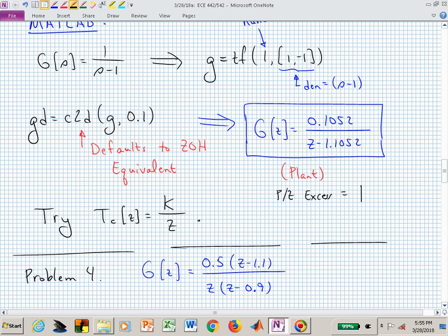Here, let's just throw that away and say, let's just put them at the origin. Let's have a deadbeat response. Let's not mix all of these different. But in real life, you would want to be mixing all of these. And on the exam, you'll probably have a mix of finding these Z deltas and using those to design a capital C of Z.